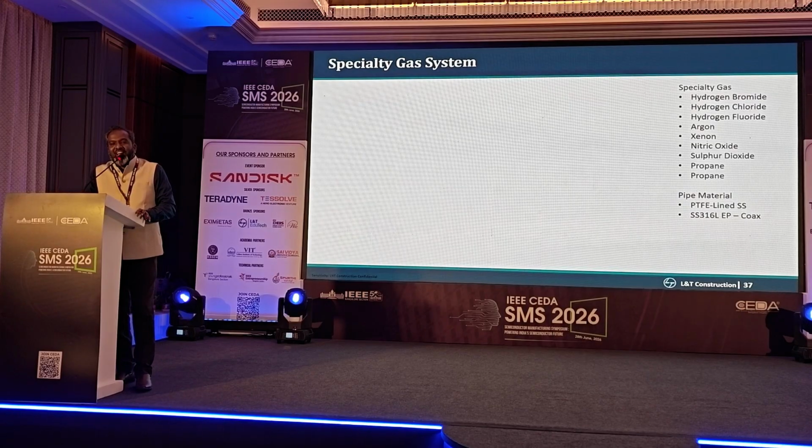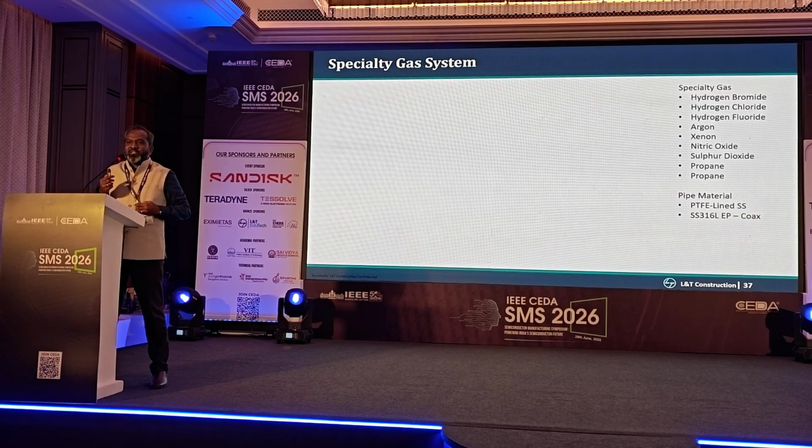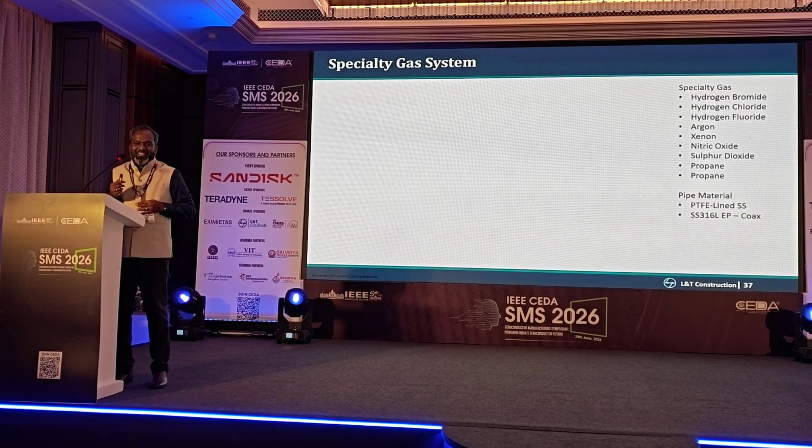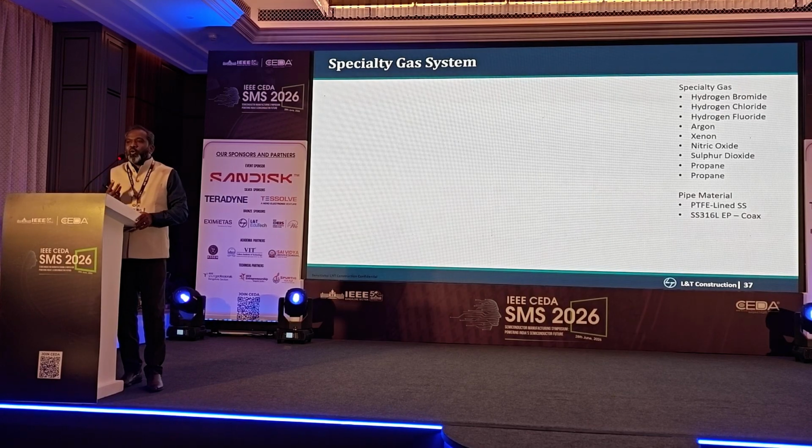Specialty gases have to be handled very carefully. It's not bulk. We are talking of hydrogen bromide, hydrogen fluoride. Just remember this word, you can go and Google what hydrogen fluoride does. Propane, sulfur dioxide, nitric oxides. So the pipe transportation system is PTFE lined SS pipes. Because this is so corrosive, this will eat away anything that comes into contact.